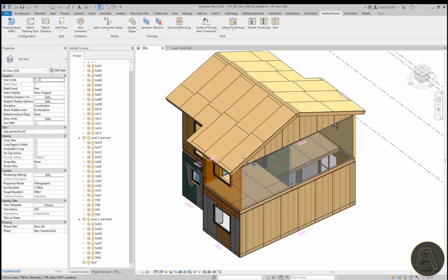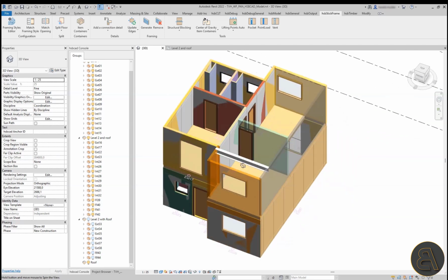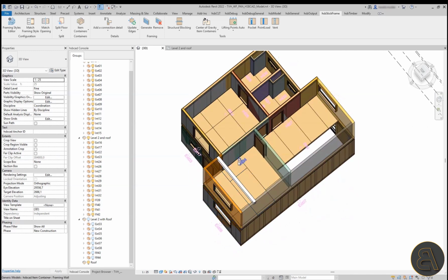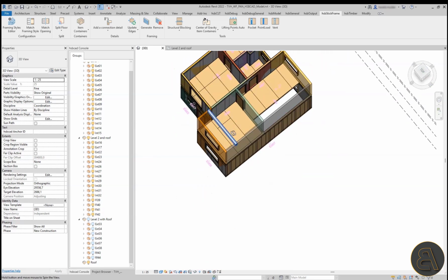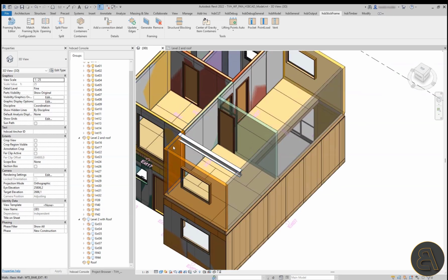I'm going to press OK in the framing styles editor, and now I want to specifically frame those walls. So I'm going to turn off my second level so I can have a better overview of my walls up here. As you can see, there are already some item containers everywhere, and there are framed walls that are already inside the model. But I want to specifically frame this one, that one, this, that, and that wall.